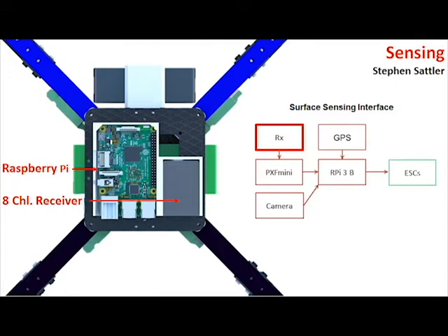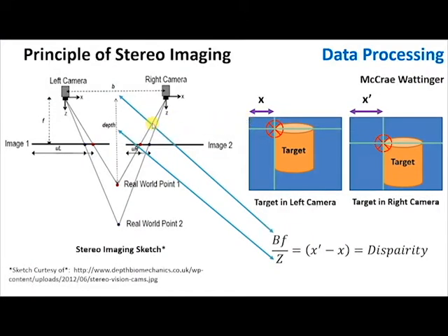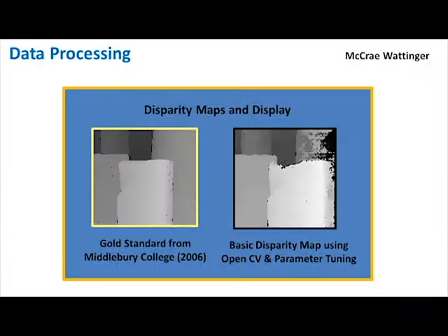enabling everything else. The purpose of the data processing subsystem is to take spatial data and images collected by the stereo imaging subsystem and relate them via similar points on the same object within both images. The difference in indices between these points is known as the disparity and can be used to generate a depth map.